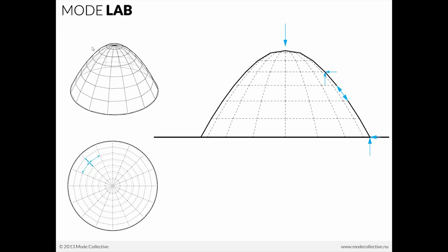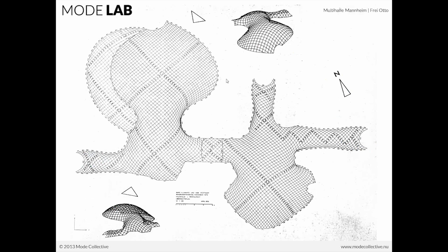But whereas the tension system also had opposite curvature in the two directions that composed that surface, in the grid shell the curvature is going to be consistent. They'll both be curving in the same direction no matter which way you're traveling through the surface. And a grid shell really gets all of its strength from its double curvature. Okay, so some examples of a grid shell.